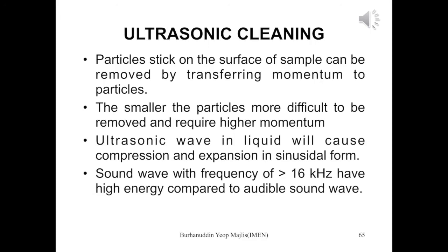Ultrasonic cleaning is used to remove particles stuck on the surface, which can be removed by transferring momentum to the particle. The smaller the particle, the more difficult it is to remove and the higher the momentum required. So ultrasonic waves are used. Ultrasonic waves in liquid cause compression and expansion in sinusoidal form. Sine waves with frequency greater than 16 kilohertz have high energy compared to audible sound waves. So we normally use this frequency for cleaning.